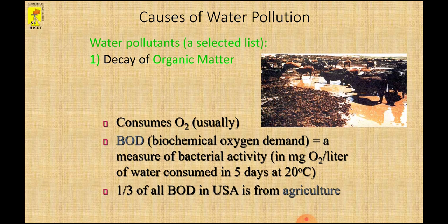It is necessary to ensure that the treated water has at least 4 milligram per liter of dissolved oxygen before its disposal into the river. And the dissolved oxygen is vital for the support of fishes and other aquatic lives in river water.